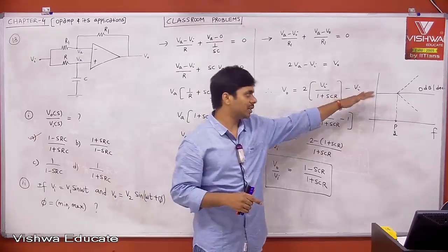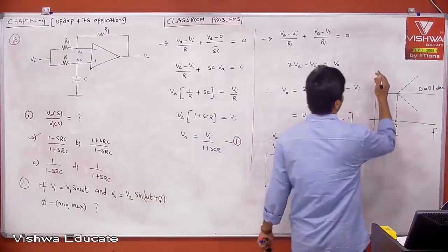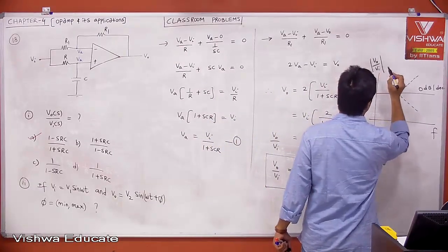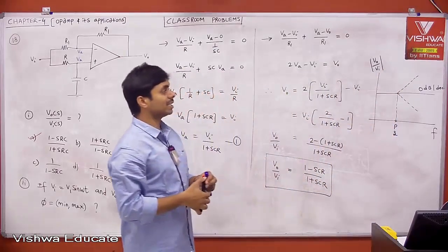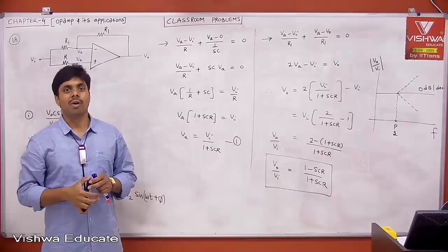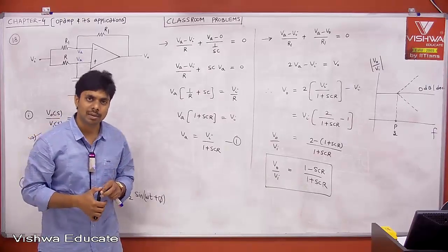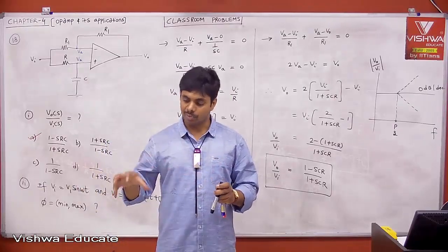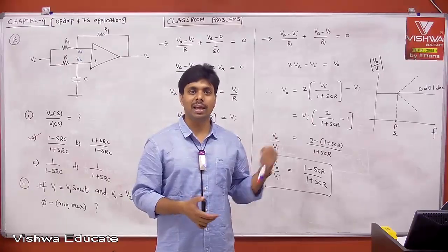Yes, this is an all pass filter, but this is the magnitude response. What do you mean by magnitude response? This is your magnitude response, but this is used to give a delay. We want a delay element. This is nothing but an analog delay element, passing all frequency components with some delay. Therefore, your output is equal to input with some delay. That is your delay element.